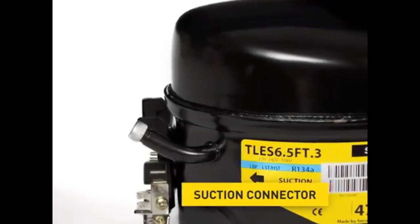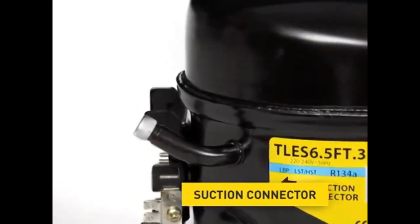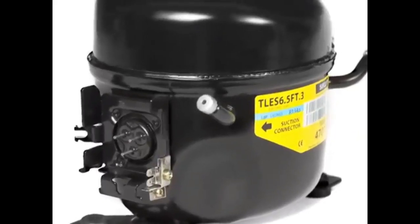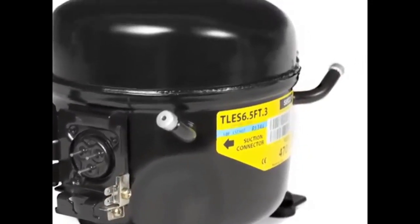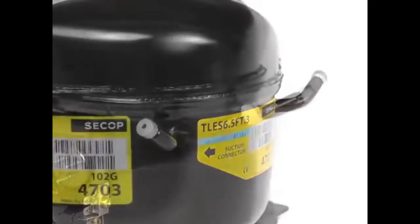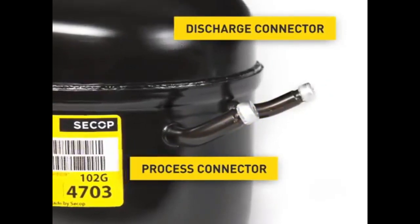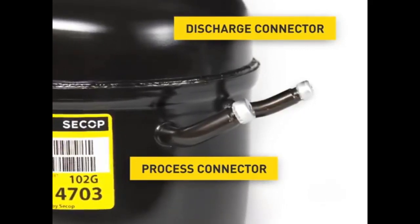The suction connector. It's connected with the refrigerating circuit of the respective appliance. Coming from the evaporator, the refrigerant is sucked in through the suction connector. On this compressor, the process and the discharge connector are on the opposite side. The process connector is used for charging the appliance with the refrigerant.